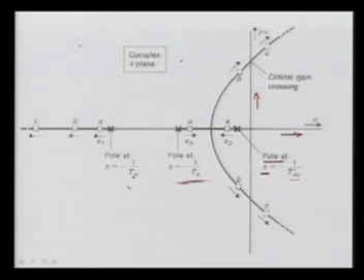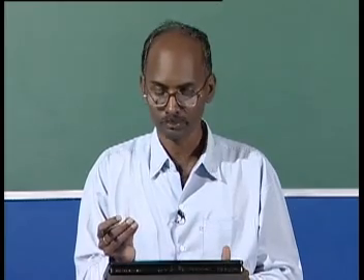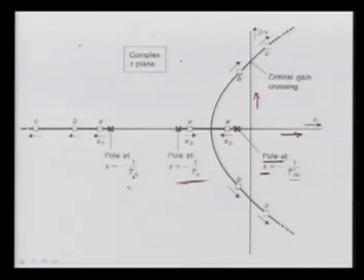Now, at these cross points the gain is equal to 0, which is called open loop gain. If you keep on changing your gain, then the movement, as I said, will go to point A. If you again increase the gain, you will reach point B, going in this way, and the system is still stable. But again, if you increase the gain, let's suppose to point C, then it can cross the axis here, and then your system, your AVR, will be unstable.